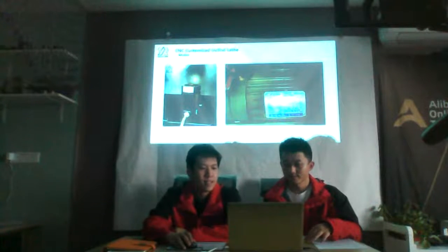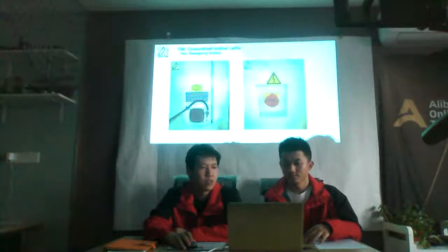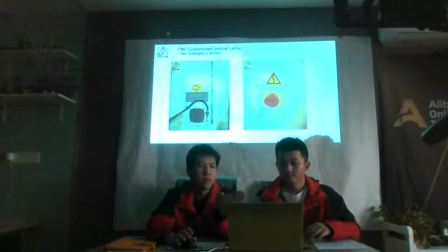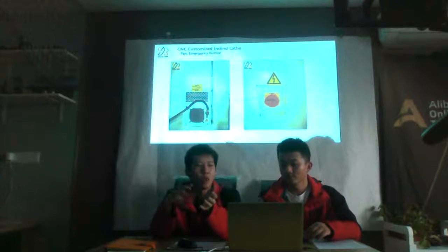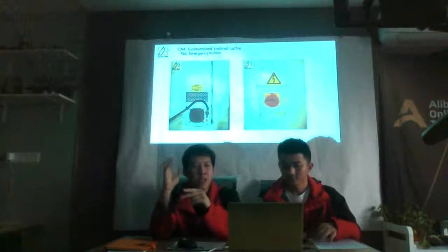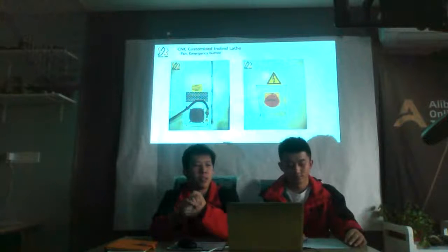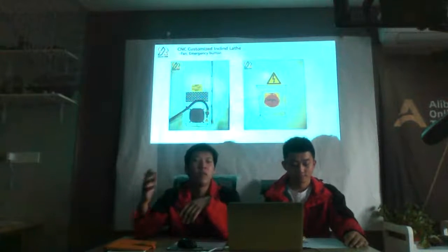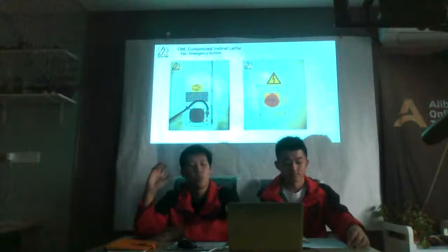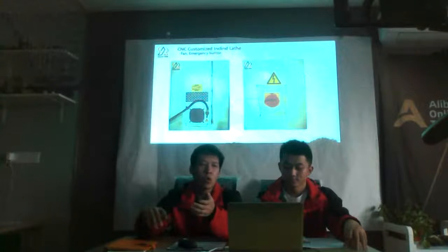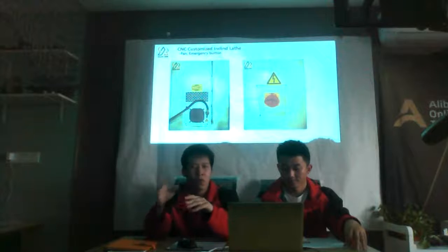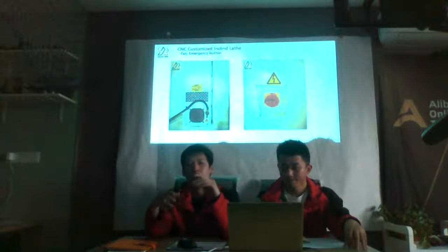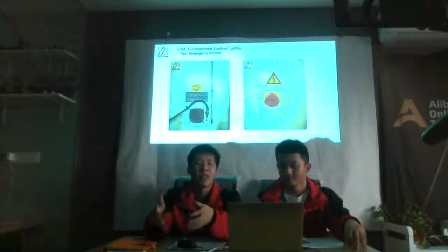Yes. And this is the machine's motor, and this is the machine fan and emergency button. You can see them. One fan is attached on the back side of the machine, and the emergency button is usually on the right side of the machine. Sorry. And when the machine is getting overheated or too much process, the machine is not under control, you hit this button and it will stop immediately.